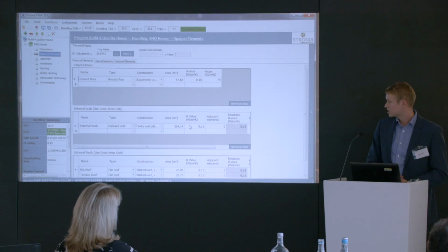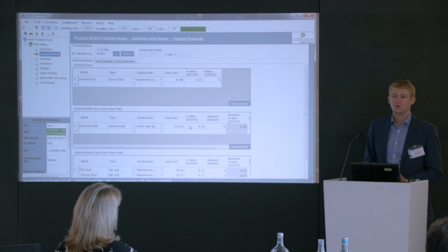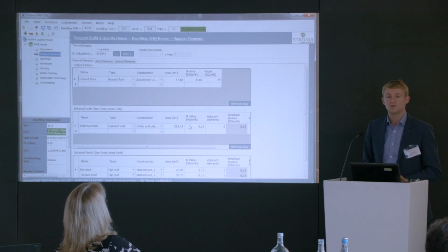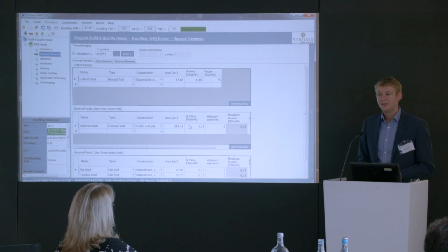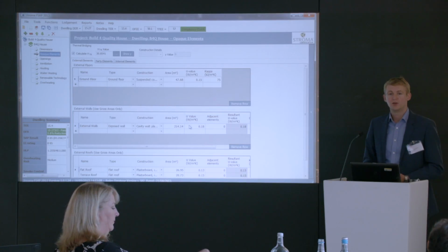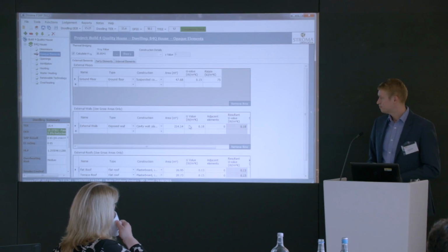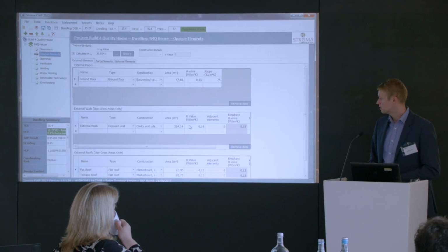Next one we have is an external wall, and the U value there is 0.18. That is the same value that gets assumed in what SAP calls the model design. Now, the model design is basically the specification it uses to work out your target emission rate. So what we're saying here is that what we're proposing to do with the external wall is exactly the same as what SAP is assuming when it works out our target. So we're not being penalised, but we're not getting any benefit either. 0.18 in masonry construction, probably 340 mil width, something along those lines.